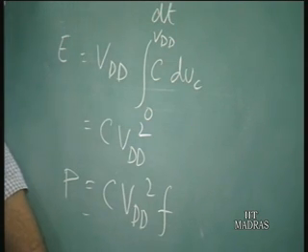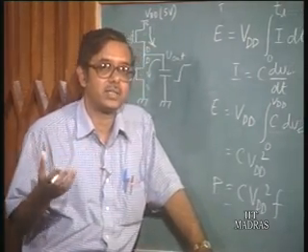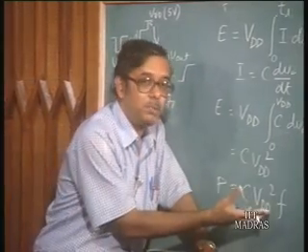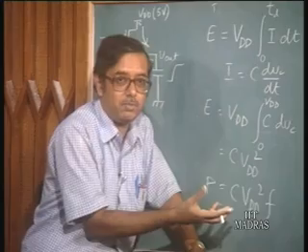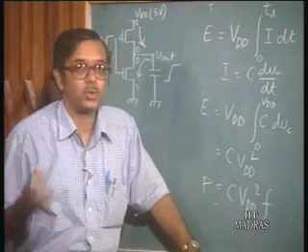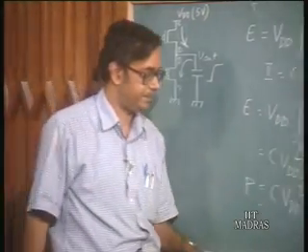the static power dissipation is basically a wastage of power. You are not doing anything. So in the CMOS, that way it is very efficient in the sense that the power dissipated is actually useful power, used for switching purposes, and there is no power dissipation when the circuit is not changing state.